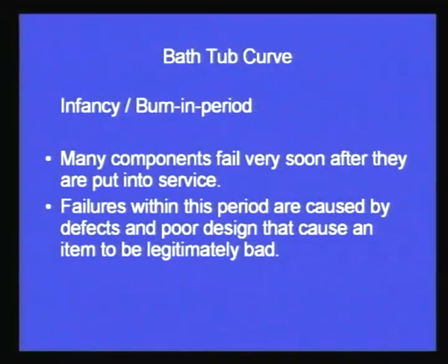So we say that at the inception stage only, because of some wrong design or some wrong software development, the product is not able to perform its intended function. Because of the poor design, the product fails as soon as it is asked to perform its function. That is basically the burn-in period, in which we have seen that initially the failure rate is very high, but with the passage of time this failure rate reduces.